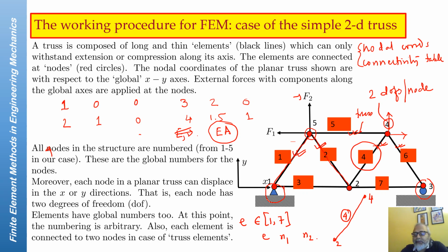They are slightly different in spirit from solid elements that we are going to learn about later, with which you mesh a complete, say, half space or a complete solid object. So those solid elements are slightly different in spirit from structural elements like beams, plates, shells, trusses, and so on. For these structural elements, many a time we will apply forces at the nodes.